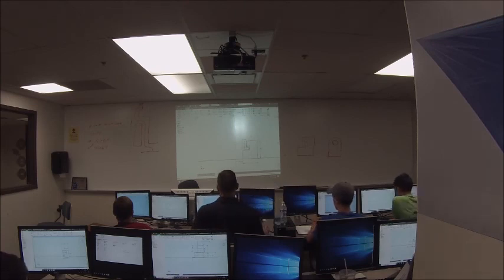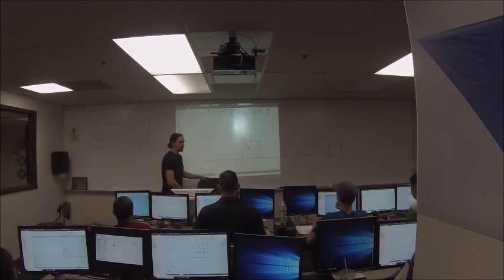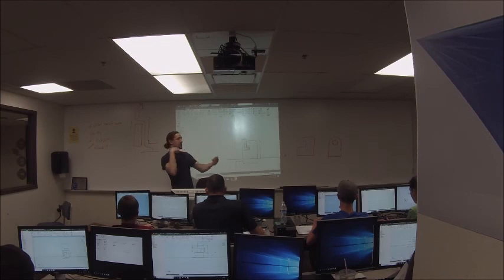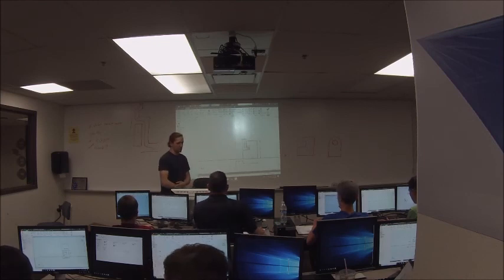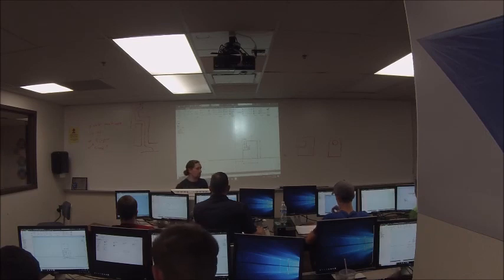Alright, guys, we're gonna move on. I think all of you pretty much have the shape that I have on my screen. All right. So in order to revolve something, we have to have a center line. We have to have a line that acts as the axis that we revolve the thing around. Okay. So now that line can be part of a profile.